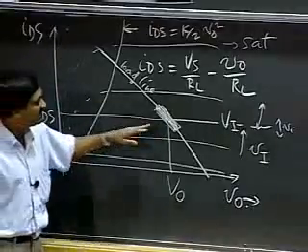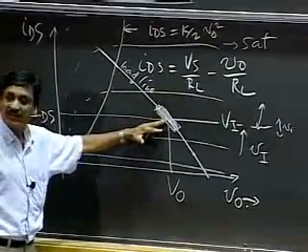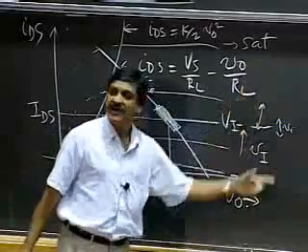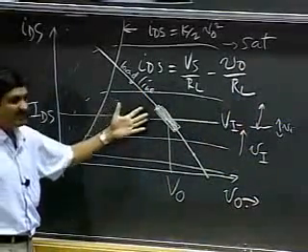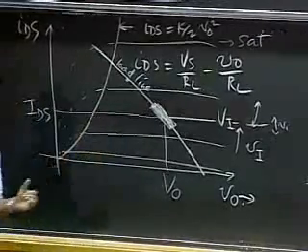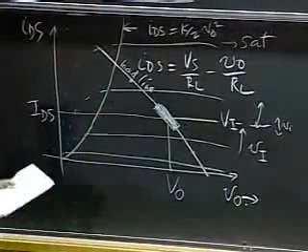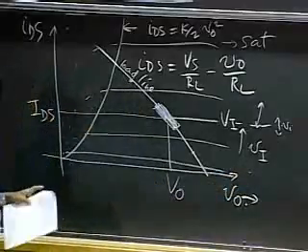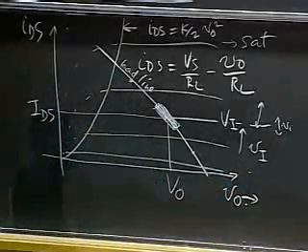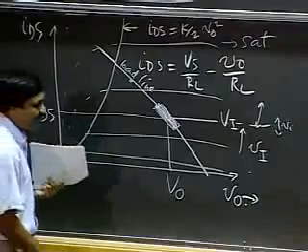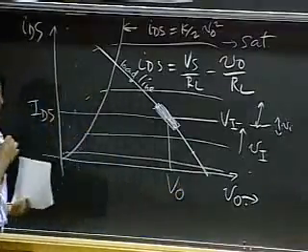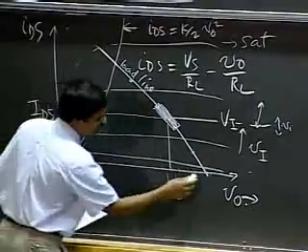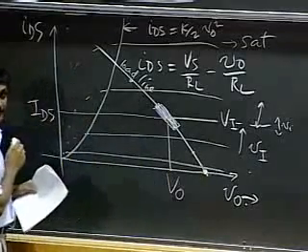Notice now the operating range: how far can VI vary before the MOSFET goes out of its saturation discipline? Well, on the low side, my VI can come down, and we looked at the operating ranges for an amplifier, all the way down to VT. At that point, the output will come here.